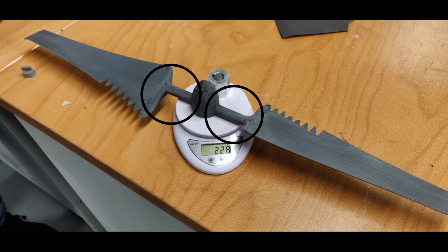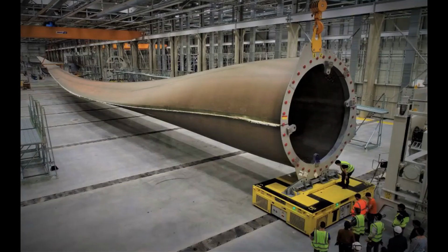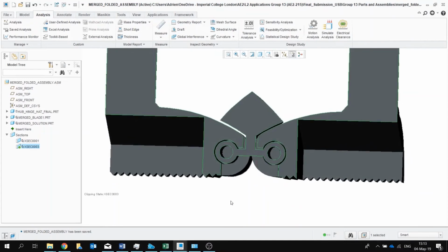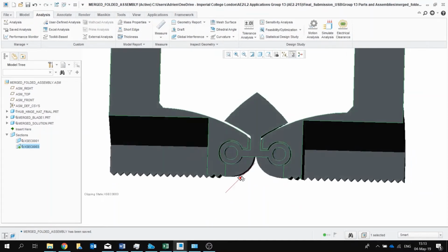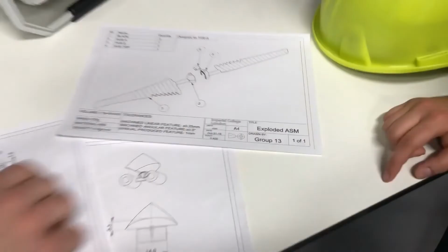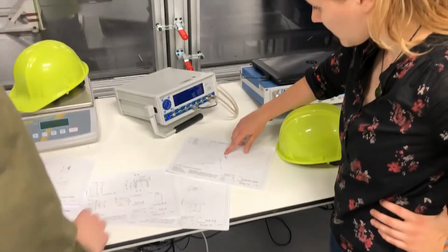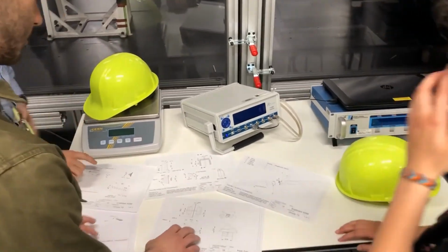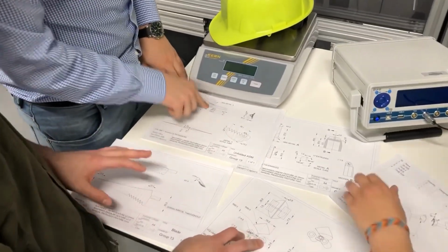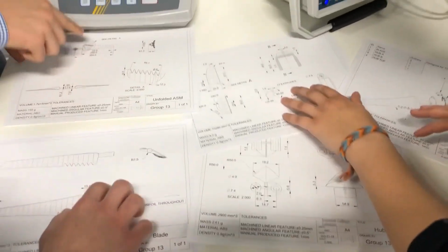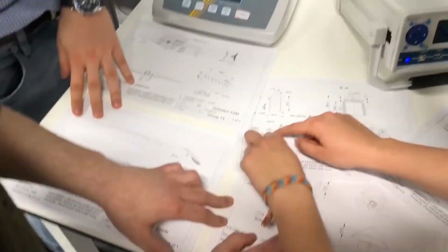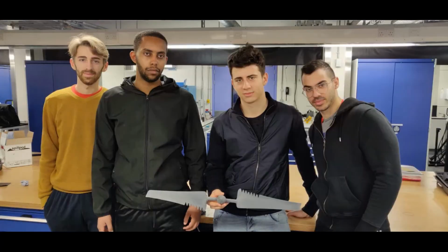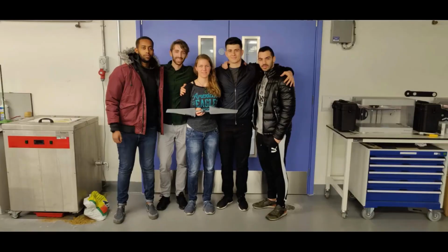It may be worthwhile to revisit this design, looking to optimize structural and aerodynamic efficiency of these sections, just as industrial wind turbines do. The hinge worked very well, and the chevrons fit smoothly. The walls around the hub were definitely too thin. To improve on this design, it would be interesting to redraw the nose cone, adjust the root section shape, and drill holes into the metallic hub to reduce weight. Vibration analysis could also help determine the onset of resonance and reduce amplitude. Overall, we're very proud of our design, but recognize the few faults it presented.